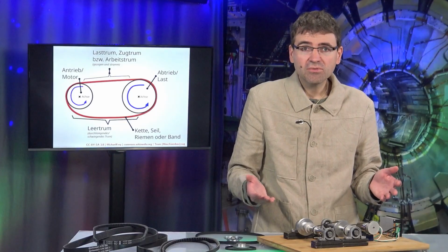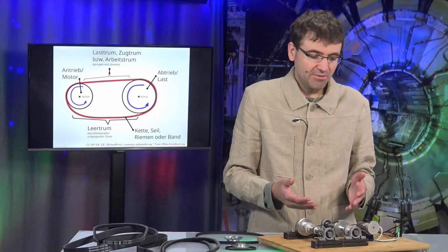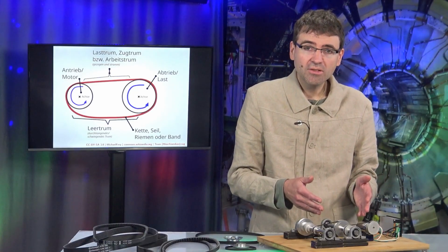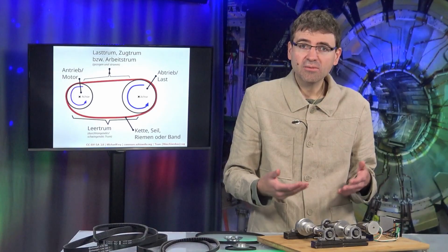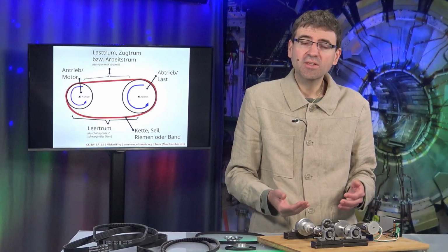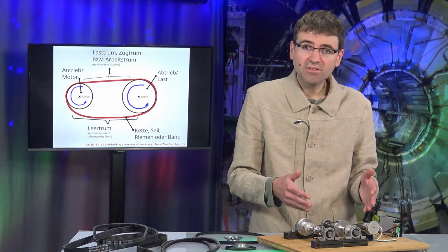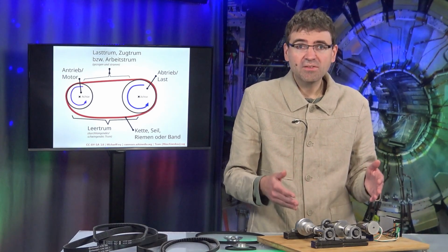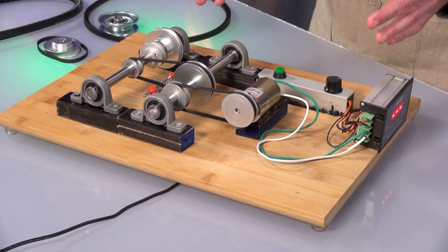We always need a measuring device and must perform a measurement. When we set up a system, it is briefly commissioned, then it runs in for a period, and after a short runtime, we must use a measuring device again. We must check if anything has changed, or if the system works. If something has changed, perhaps we need to adjust the tension, or can everything remain as it is?